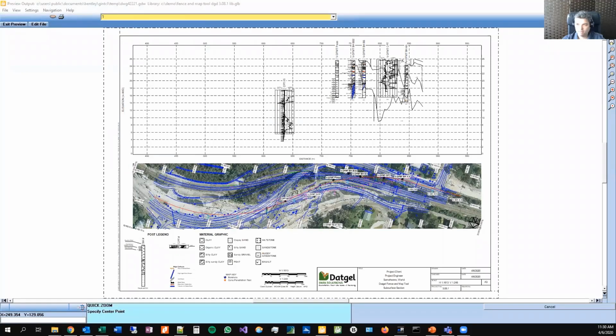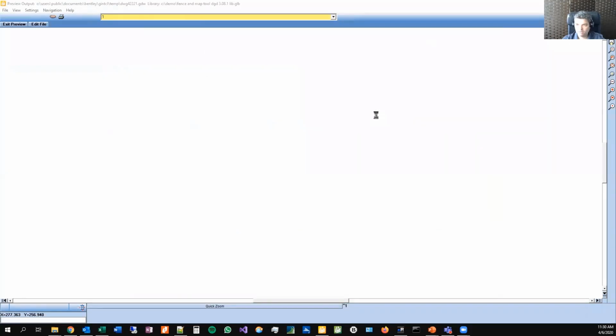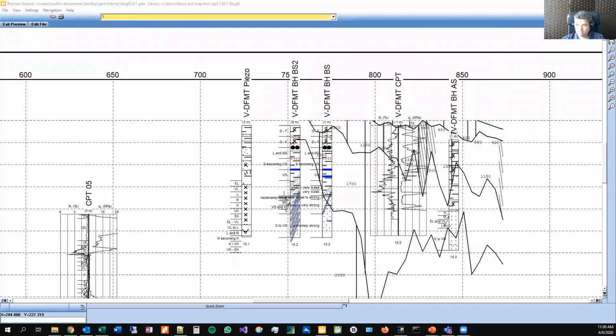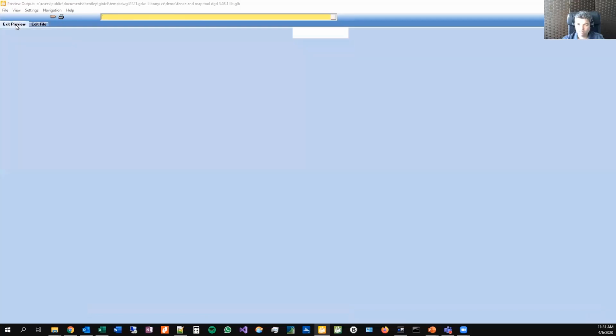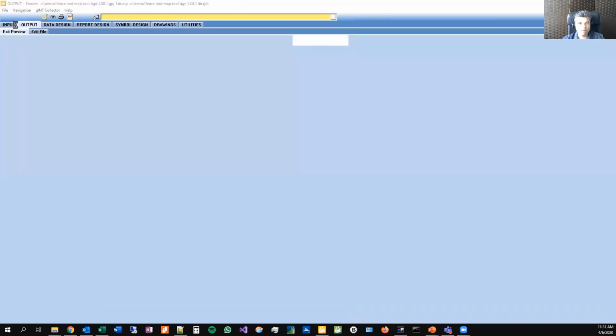All right, so this time we have the air photo, and we have, zoom in here, we have the major defects. And it's a bit of a mess, isn't it, at this scale? But this is the geophysics, the seismic refraction data coming from the fence drape. So it might be good to make that a different color. And you can set the colors in the drawing interface. Okay, so exit that. Now we'll just briefly show a map, right, to wrap this up.